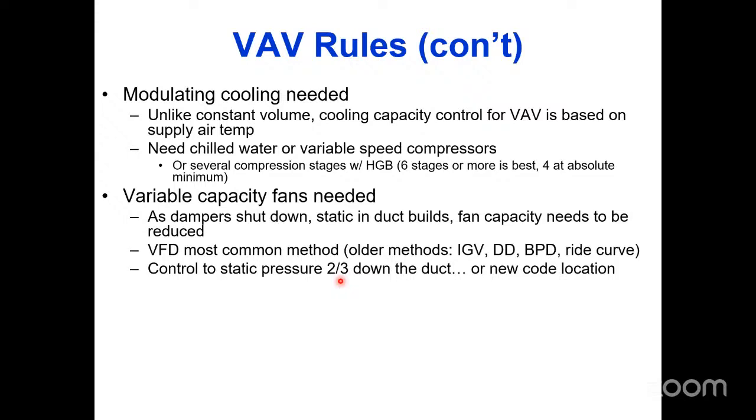No problem. You cannot put it at the discharge of the fan. That's the worst thing. The fan will essentially never ramp down, or it'll ramp between 90 and 100%, which is crap. You don't want that. You want this thing to be able to ramp down to 20, 30, 40% when needed. So you got to stick it 2/3 down the duct.